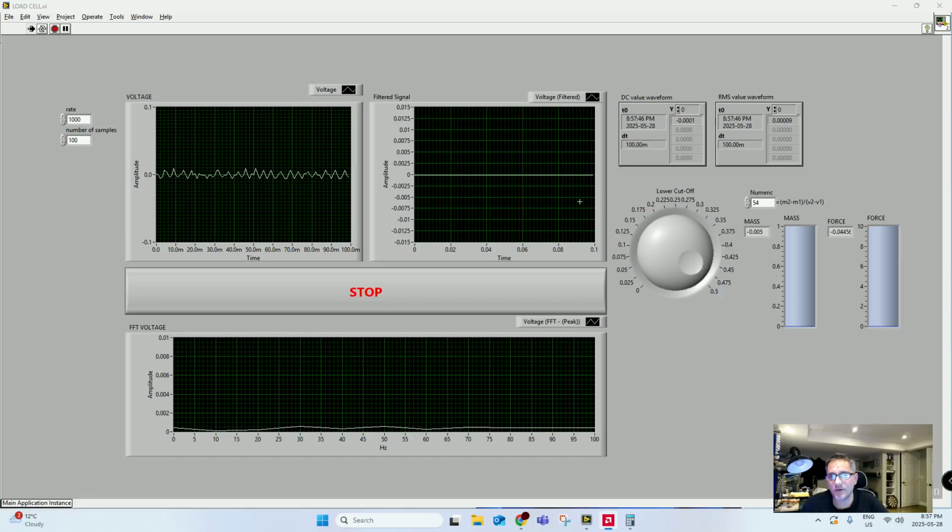It has been filtered in order to avoid those fancy oscillations that can make the signal fluctuate excessively. It's the same technique that is used in those tools that cost between 300, 500, even more dollars, by implementing a substantially lower cutoff low pass filter. I use a Butterworth filter to prevent oscillations like those occurring here naturally from affecting the measurements.